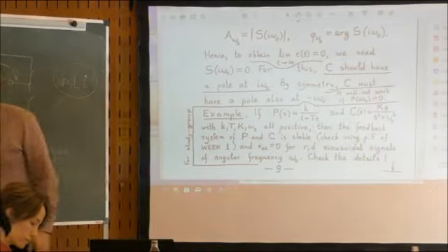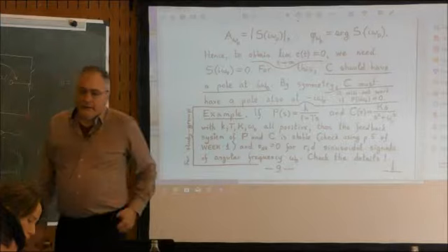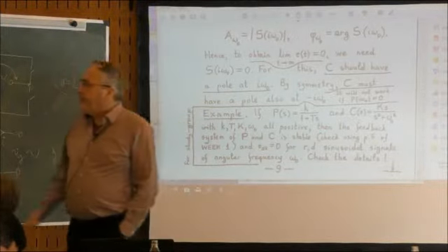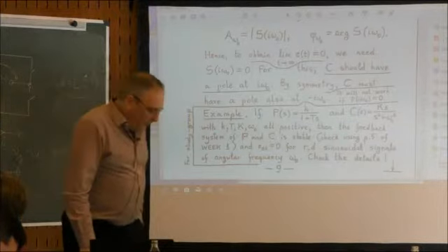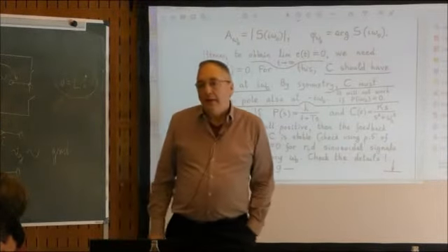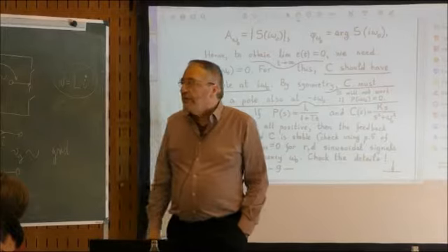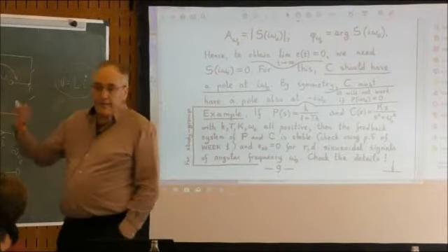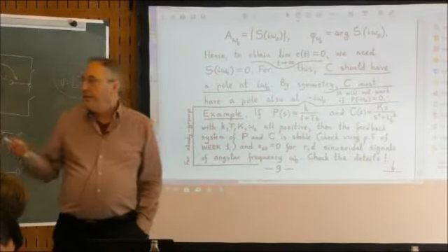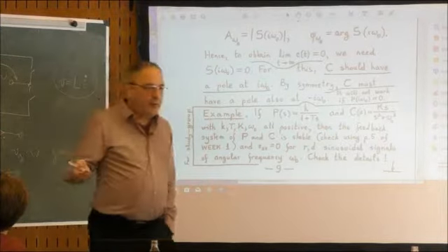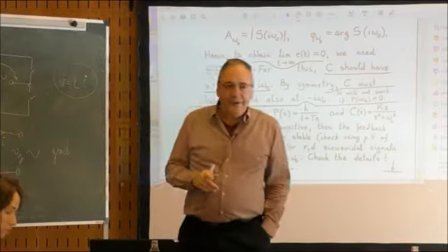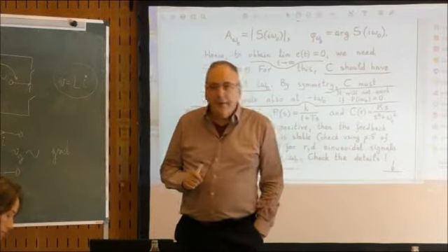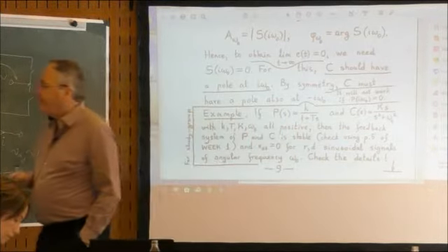Now there is a little discussion here which I have not gone into, namely how to determine this reference signal R. You could say, but it wouldn't work, that it is a constant times the grid voltage, but that is not correct to do it that way. It's actually more complicated than that, for several reasons.